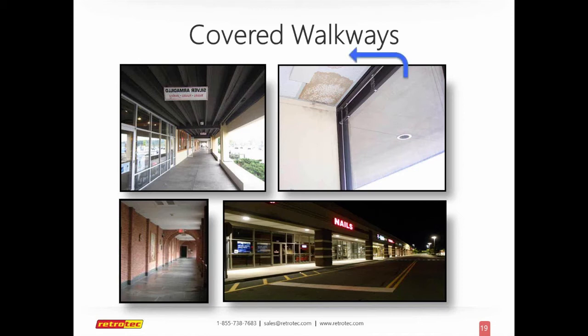So again, I have different temperature of air coming in, right? It could be hot, typically it's coming in, connecting with the ducts, the water pipes, condensing, dripping. Now next time you go into a facility, dentist, doctor, tax accountant, whatever, and they've got the drop ceiling, take a look at these stains. Many of you may realize that they're probably not roof leaks. They're a condensation issue. And condensation issue usually means they have some kind of air leakage.